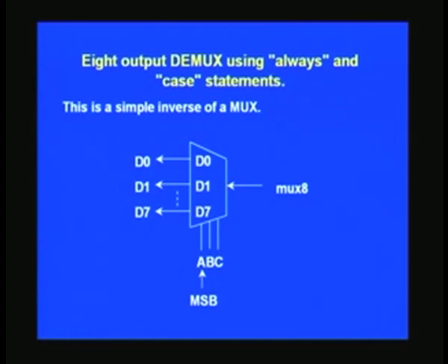So this is, as I said, the inverse of mux 8. That is the reason why I am putting mux 8, which is the output in the earlier case, as input here. So naturally, after this process, you get back what you have plugged in as inputs there. So this D0 should correspond to I0 and so on, I7 to D7, and once again here you have the selector,